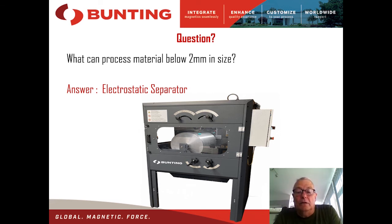The question you may have after watching this: what do I do if I have conductive material below 2 to 3 millimeters in size? Well, the answer to that really is an eddy current separator's performance will drop off below that particle size range.